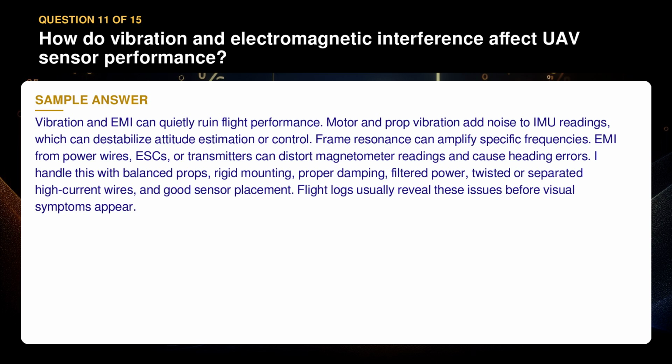I handle this with balanced props, rigid mounting, proper damping, filtered power, twisted or separated high-current wires, and good sensor placement. Flight logs usually reveal these issues before visual symptoms appear.